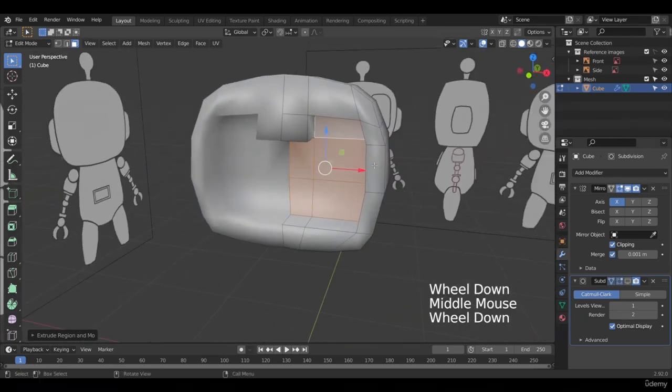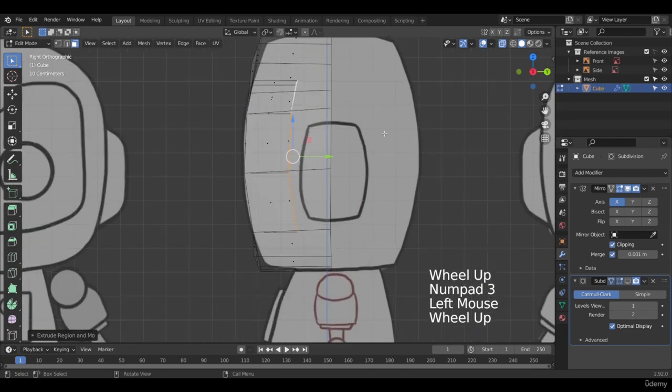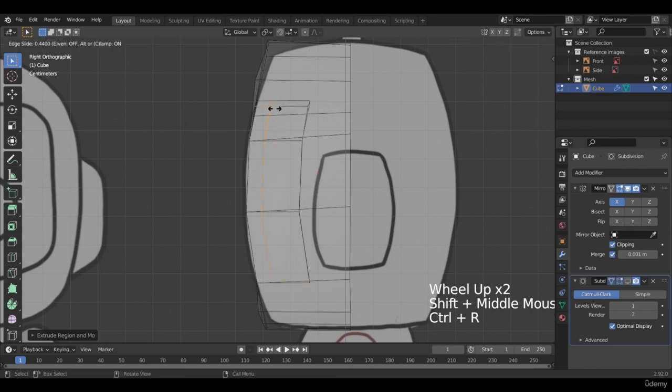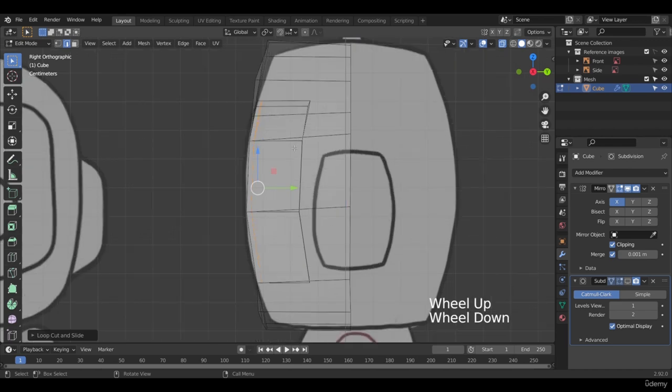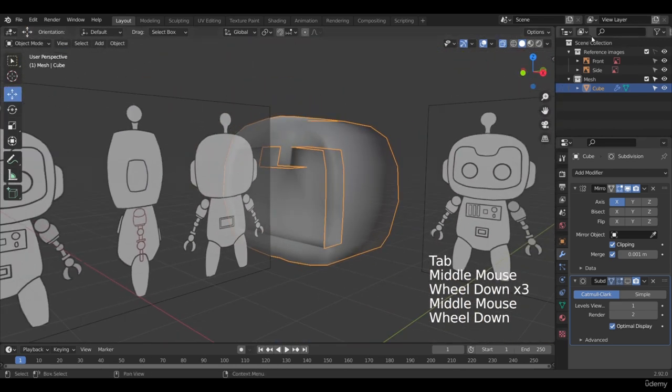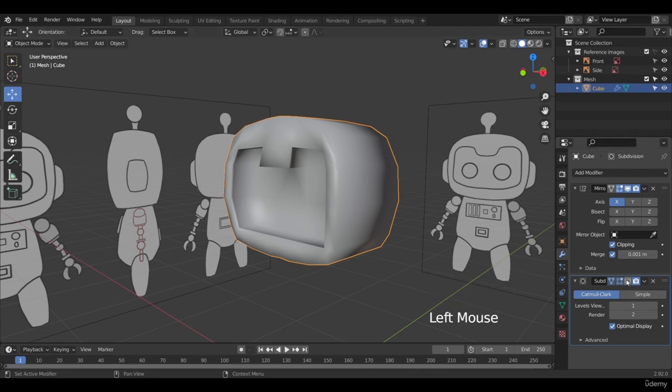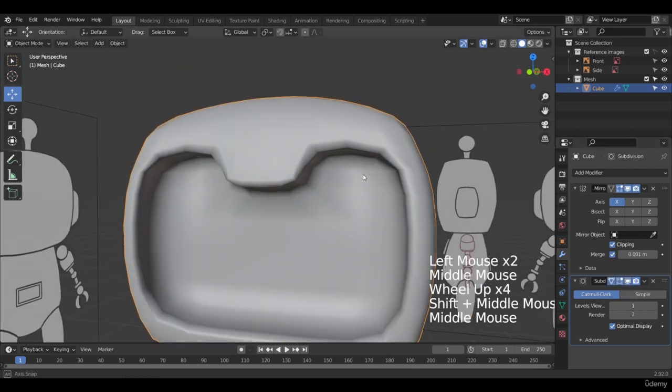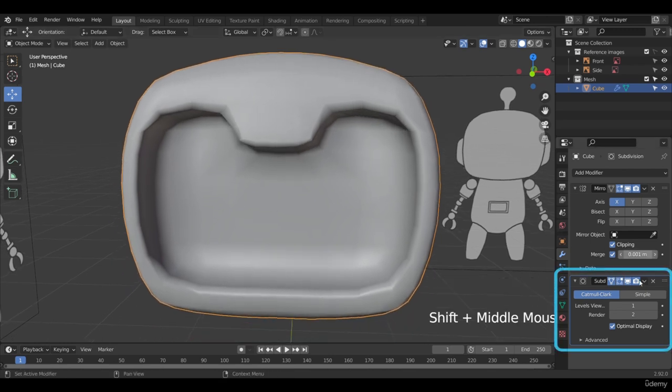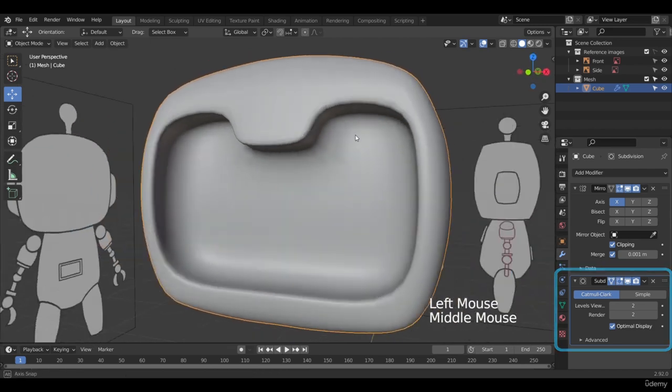One thing that I want you to do is to create another loop cut, but right here, at the beginning of the extrusion, so the edges are not missed. I'm gonna explain later, but we're gonna create another loop cut right here. And now, this is very squared, so I'm gonna activate our subdivision surface again. And you see that this doesn't look right, and that's because the subdivision surface is not enough for us to see it smooth. So we're gonna make another level. This is right now at 1, so we're gonna put it at 2. So now you see it's much better.